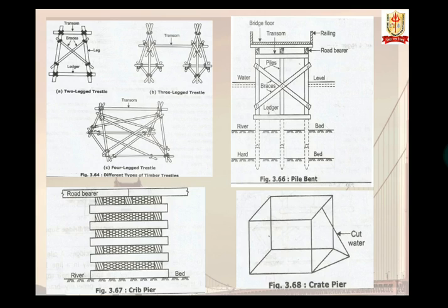Cribs. They are generally made of wooden sleepers placed in layers alternately in the transverse direction, which are then fastened with ropes or spikes. Round logs notched together can also be used instead of spikes. The bottom of the crib is planked to form a tray as shown in the figure. After constructing a crib of this type, it is floated to the site and placed in position by filling stones in the interior spaces to make it sufficiently heavy for stability in running water.